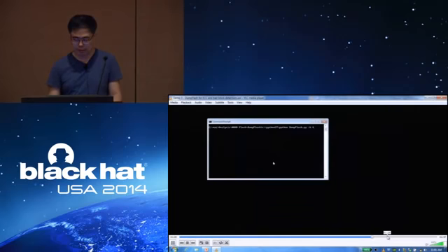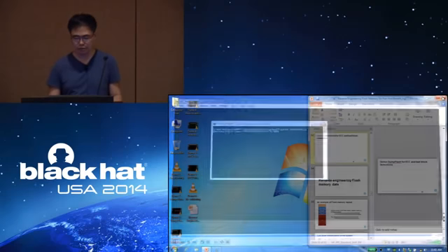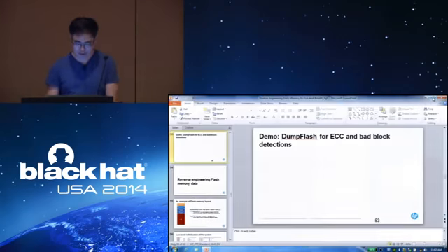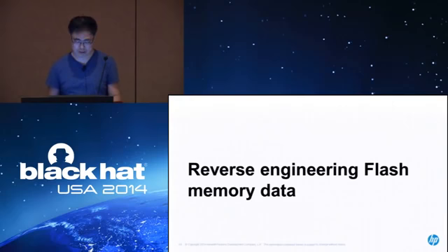So we skip, and you can pass that C option, it will check the ECCs. This operation is much slower because it's reading whole pages. For every page, it will read the whole page, and it is calculating ECC for every page. But usually you don't see ECC errors. I never seen ECC errors from the chips I worked on. So this is it. Go next.